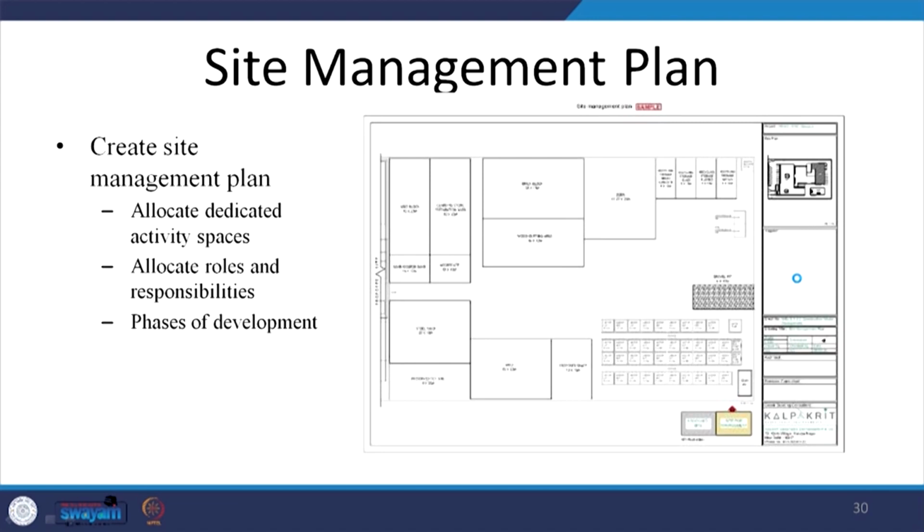Now, to implement all these strategies, a proper site management plan has to be created. Where would the vehicles enter and exit from? Where would the wheel washing happen? Where would the different materials be stacked? Where would the earth which is excavated be stacked? All that has to be developed in the form of a site management plan.